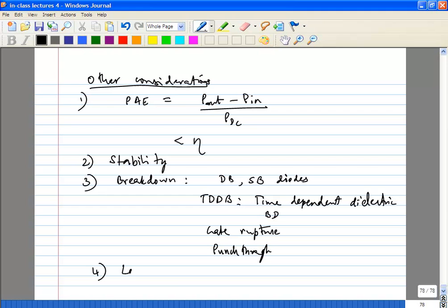And the last thing we are going to consider in class is impedance matching. The kinds of impedance matching we talked about in class were all small signal impedance matching, small signal S parameters. In reality, when you have signals of such large amplitudes, quite often your passive devices will still be linear, but the input impedance of your active devices is no longer linear. In which case you have to worry about large signal impedance matching, not small signal impedance matching.